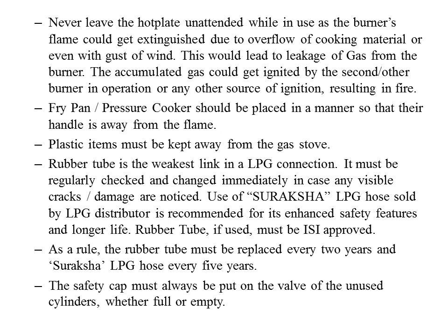So for that reason, it must be checked regularly, and if there are any damages or cracks, they should be noticed and the tube should be immediately replaced. It's usually recommended to use Suraksha, the LPG hose sold by the LPG distributor, for most gas stoves. If not that, whatever rubber tube we are using should be approved by ISI, and the rubber tube being used should be replaced every 2 years.